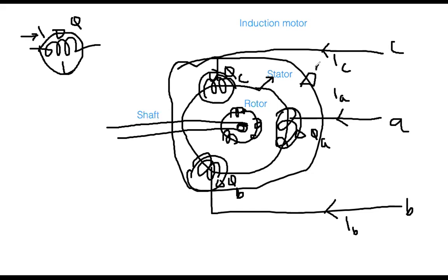I gave the name phi S, where phi S refers to stator flux. This is called the stator flux or field. So everybody see, after applying three sets of current, they are producing three sets of magnetic field in their respective coils, but then there is a resultant magnetic field. This resultant, which I have designated phi S, stator flux or field, is properly rotating, the combined one.